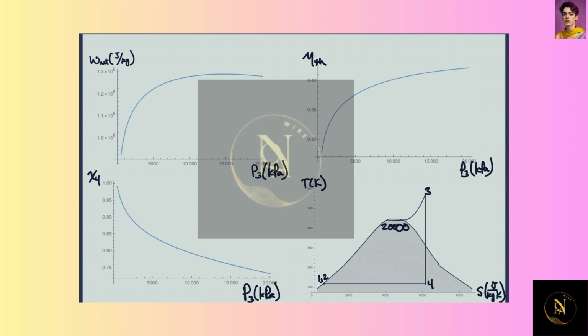If we were down here at some ridiculously low pressure, we'd wind up out here, and then coming down we'd be inside the saturation dome. That's why it goes toward 1, because we wind up way out here at high entropy levels at low pressure, but at the same temperature.